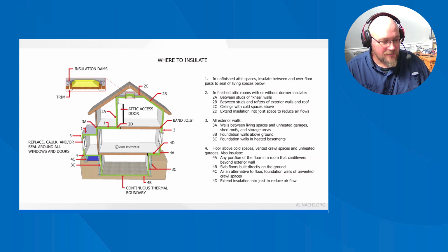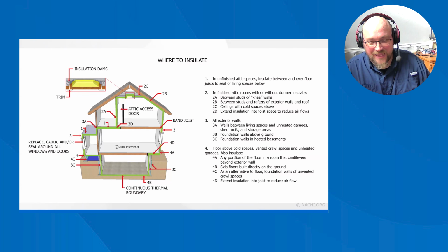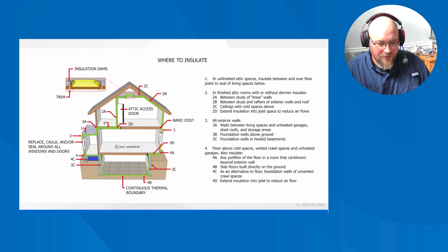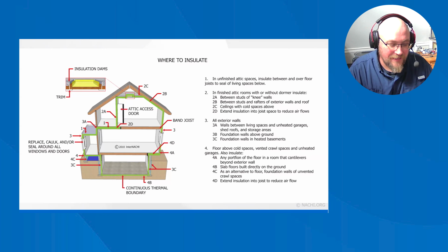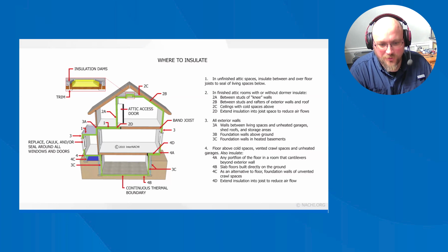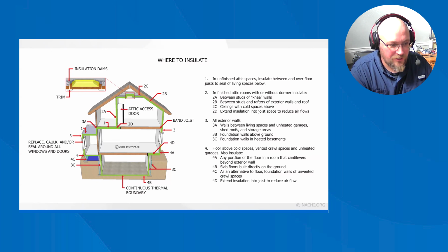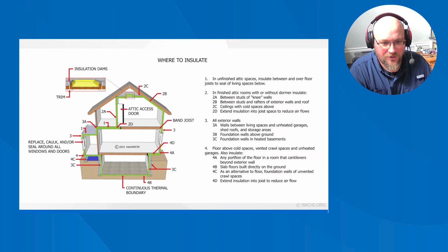So I went over there, double checked, and she confirmed that when they had the new insulation, it was blown cellulose, so ground up newspaper. They filled a lot of the electrical splice boxes that were open. And because they had older electrical wires in there, it was producing a lot of heat. And you packed insulation on top of that. Well, it created so much heat that it actually started a fire in their attic, and it burned like a quarter of their house on the backside.